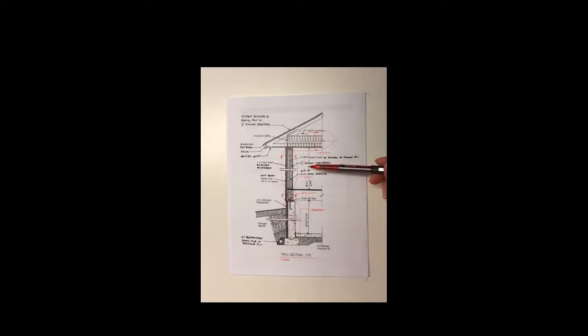So if I'm doing part 2 of this assignment, or step 2, I'm looking at that. And when I look at the outside, I'm going to have an outside air film, then my siding, an airspace, then an insulation, which is an extruded polystyrene. Then I have typically 2x4 or 2x6 wood framing. And then on the inside, I'm going to have 1/2-inch gypsum board.